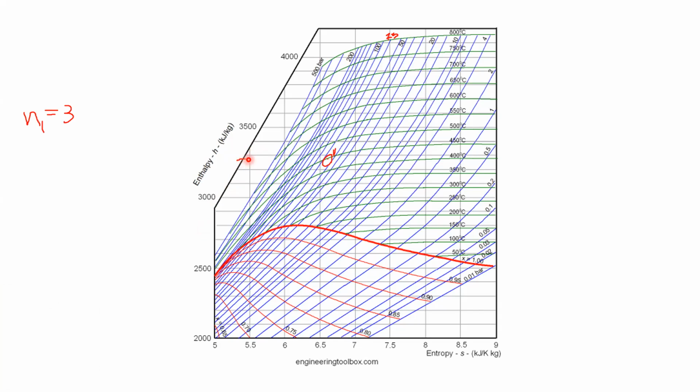It may be approximately in between, at 3280 to 3290, giving the intermediate value of these two. I am taking 3285. Usually, the unit of enthalpy is kilojoules per kg. You have to take the enthalpy units as kilojoules per kg. For this, the first point is 1.